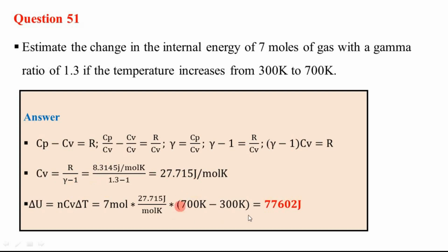Then we get the change in the temperature. Then we get the internal energy, which is positive. Positive because the temperature is increasing. I told you the internal energy is a function of temperature. If the internal energy is increasing, the temperature also increases. If the temperature is increasing, that means the change in internal energy is positive.